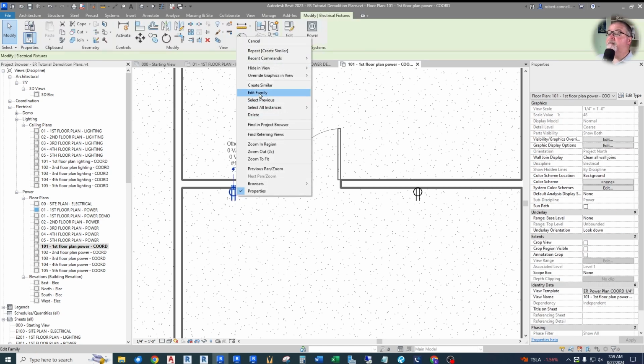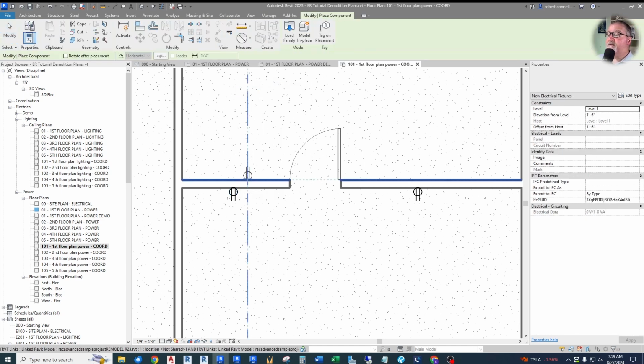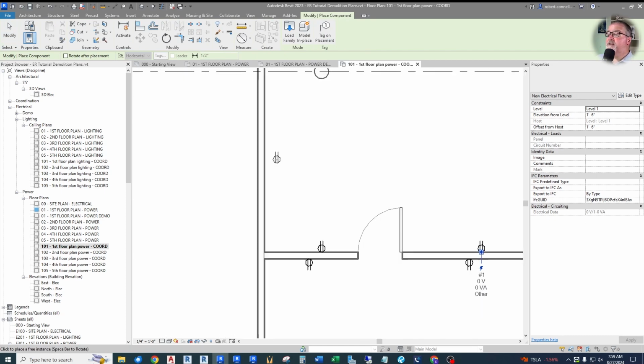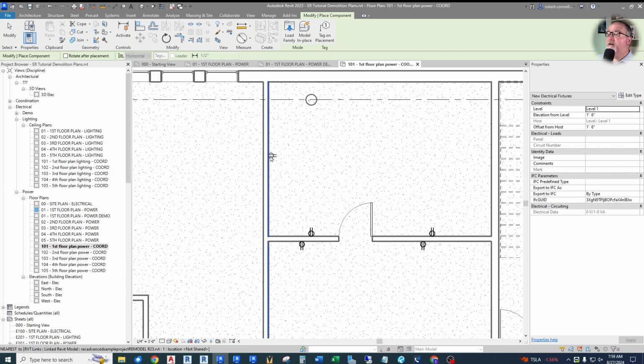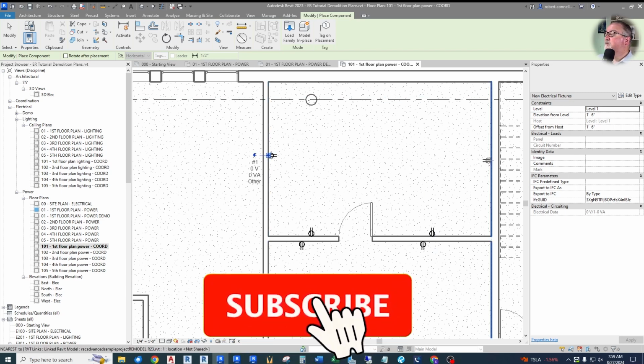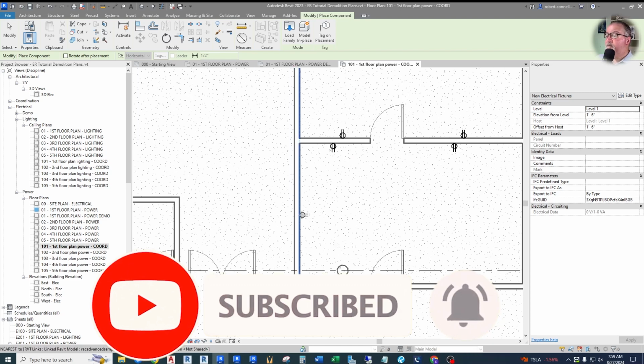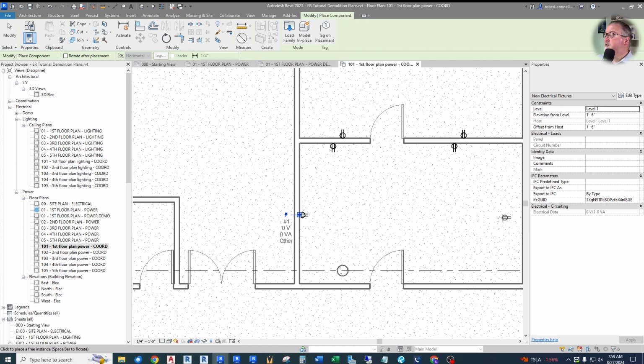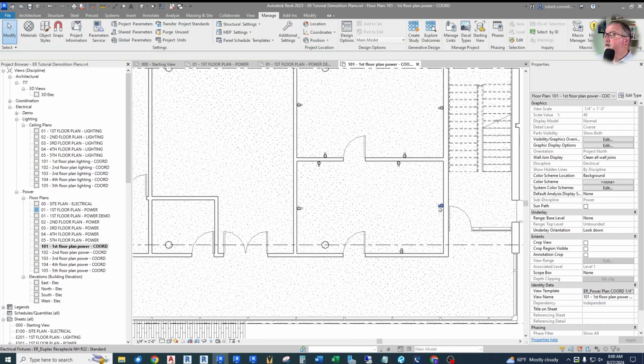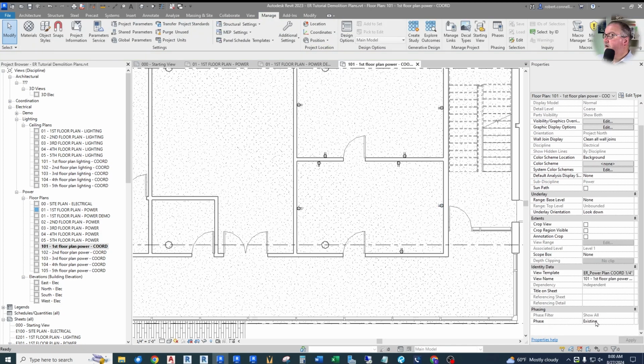Let's get the rest of these in. So again, I'm basing this on a site visit or some as-built. This is what's there now. And we even have some receptacles on these walls. I want to get those shown. I'm trying to show a complete view of this existing situation. And let's say my as-built, say there's one here. There. So those are all existing because my current phase is existing in my coordination plan.